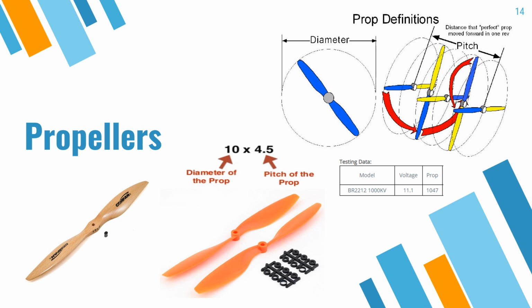If you want to go for a 3-blade propeller, which is handy because they are smaller, you could do that, but you need to keep in mind that if you have a 3-blade propeller that has the same thrust as a similar 2-blade propeller, that would be less efficient, and thus your battery runs out of energy faster.